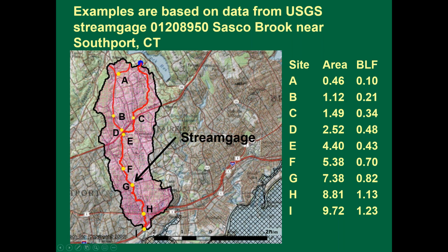So if you're putting in a new highway someplace and you have this important stream here, each of these letters might be like an alternate route across the basin. So you could easily do a dilution factor analysis to see what might be the worst case scenario. Where would I put this highway crossing that might have the greatest local adverse effect on the stream?